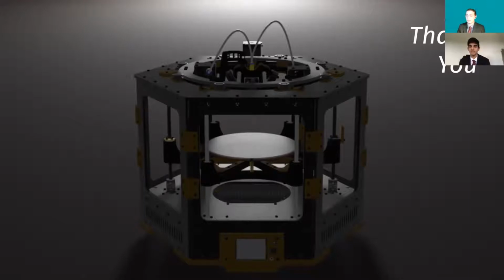A lot of the 3D printed PLA and PETG parts that make up the printer, we're going to be looking into possible injection molding as well as some SLA resin 3D printed parts. Again, so we can get slightly higher precision as well as greater longevity for those parts. And then other things we're looking for from the software side of things, we're looking at implementing some further dual extrusion support as well as support for other features with the printer from a software perspective.